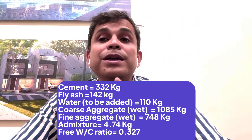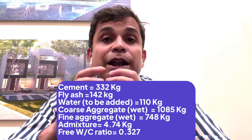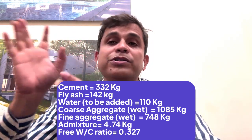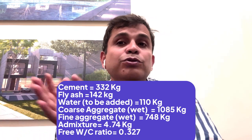So in this way you can calculate the moisture correction whenever you are doing any kind of RCC work. You need to first find out the moisture percentage, then the total percentage of moisture present in the coarse aggregate and the fine aggregate, then multiply to find the exact quantity.